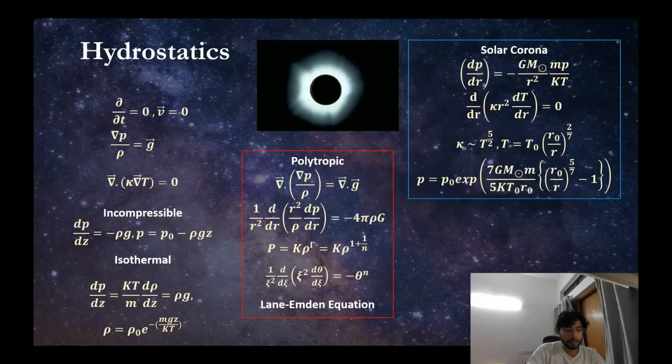So now, again, we will just use the same assumptions that we had used in the previous week as well. For example, let's consider that our fluid is incompressible. If you remember, for incompressible fluids, the rho is constant. The gradient of rho is zero, so rho is constant. So from this equation, you get dP/dz equal to rho g, and this side is a constant term.